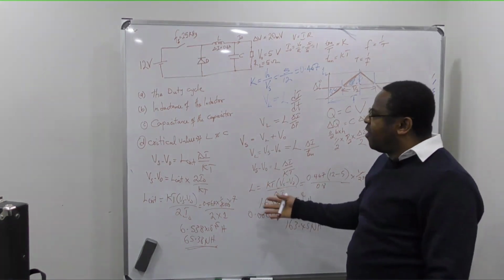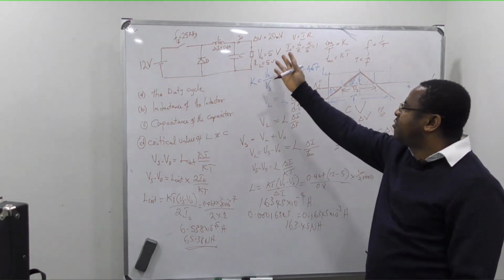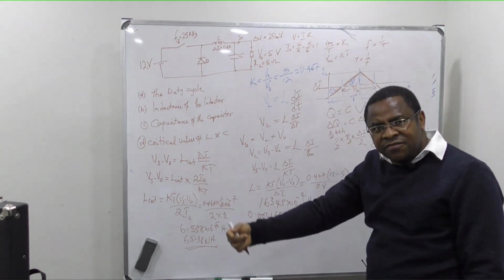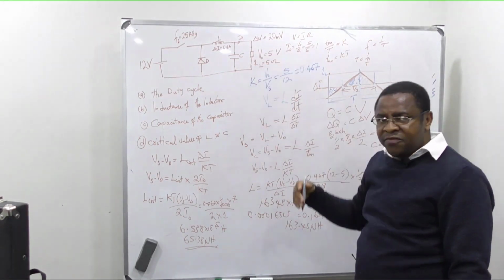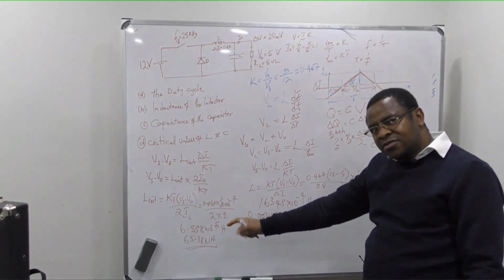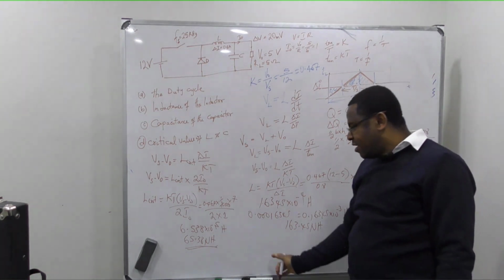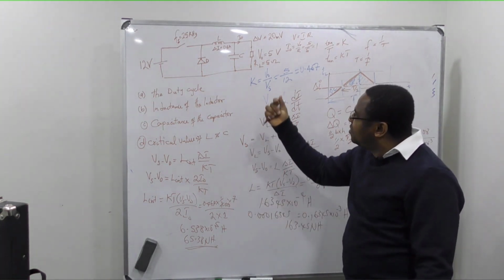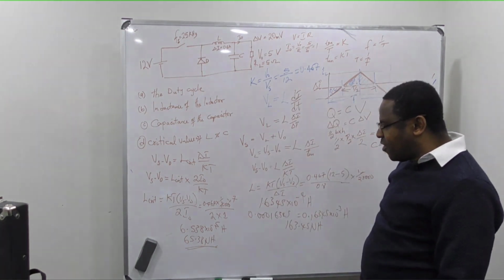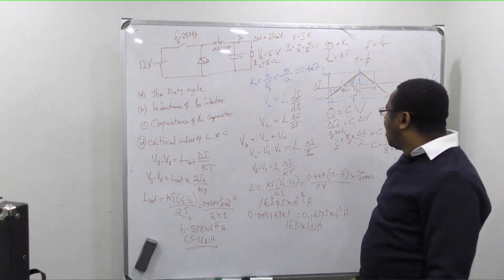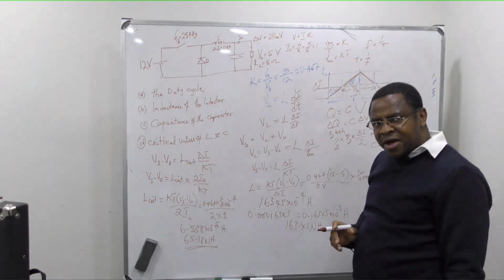While the normal, from that equation, we use this to get all those parameters. But if you are changing the value of the inductance to see how the system performs, that is a critical value. As you are reducing it, you want it to be smoother, to be better. It should not go less than that, 65.38. Now we can do the same thing to calculate the critical value of the capacitor.